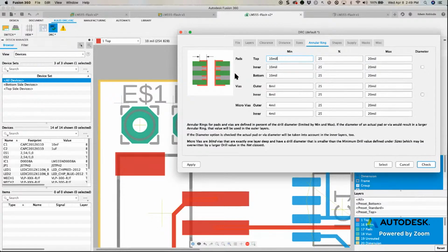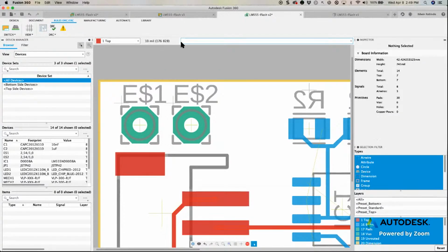What happens is that once I place a through-hole pad on my board, it has a drill hole size, which is brought up from the library. This is the size of the hole that was determined when I was creating the component in the library. The amount of plating material is this donut effect that it creates here. This is the amount of plating for the board. In other words, when a trace attaches to this,